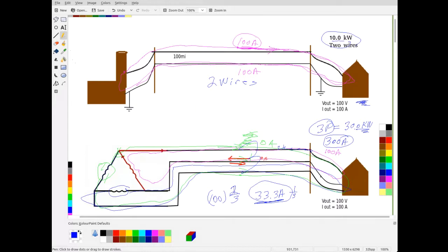And when we think about the resistance in this wire, and we talked about that huge loss due to that resistance, if I can reduce my current by 1/3, then I'm going to significantly reduce the power loss here. So by running just one more wire, I can either triple my power or reduce my current by a factor of 3. Either one of those is a huge gain.